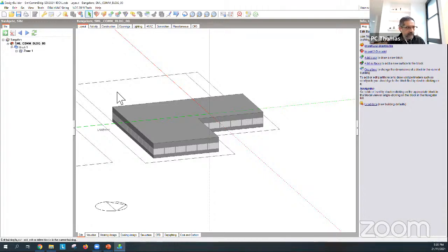And the way I'm going to do that, I'm not actually going to change the U value. That is, I'm not going to change the characteristic of the window to reduce heat transfer because of temperature difference between inside and outside. Instead, I'm going to change the way that it lets solar radiation come in.